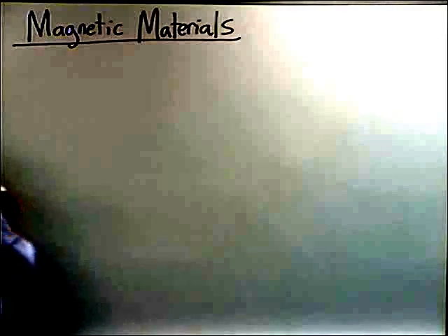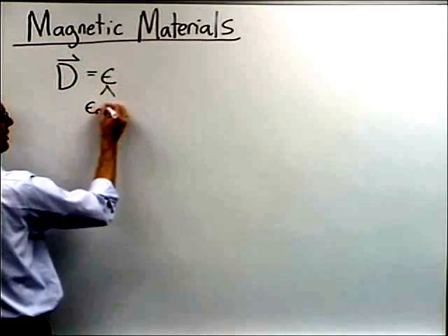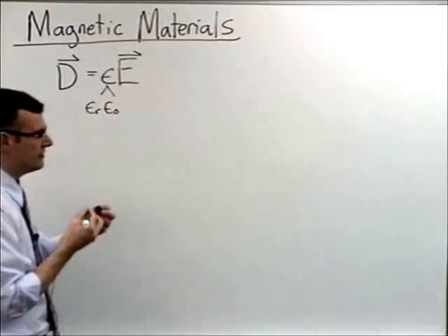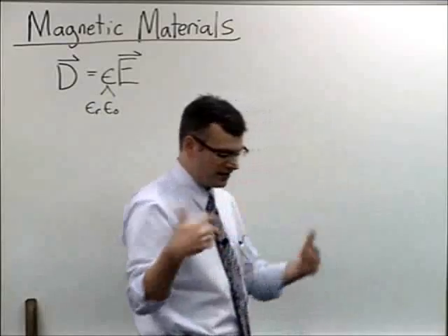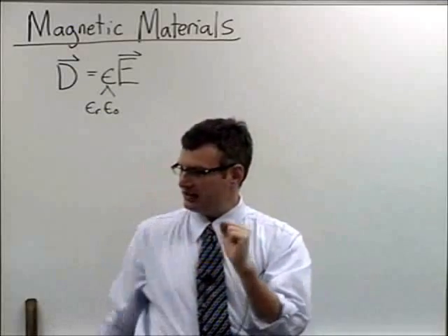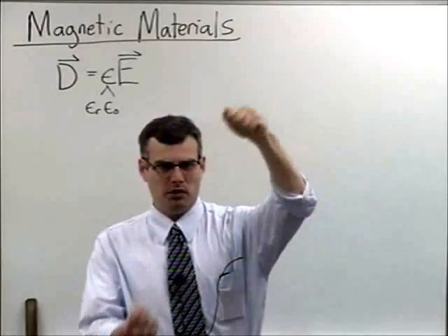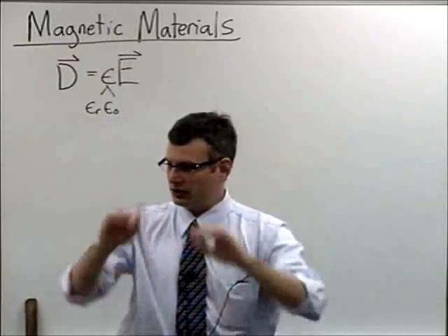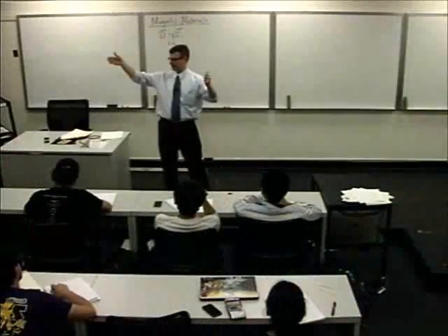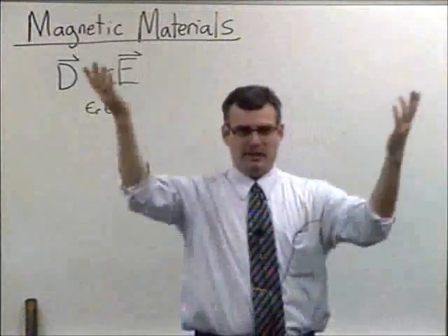We know from electrostatics, our discussion back then, that electric flux density is equal to epsilon, which we often write as epsilon r, epsilon naught, times the E field. And of course, epsilon r is always greater than 1. And we have a nice way of thinking about that, right? We understand that when you impress an electric field onto an atom, you're going to pull the positive nucleus in one direction and the negative electrons in another direction, kind of like a rubber band, and they'll snap back into place. The pulling of that dipole apart makes a countervailing electric field, which suppresses the total impressed field, and that means that the total electric field will be less than the original proportionality with the electric flux density. Hence, that constant of proportionality is bigger. You'll have a smaller E for the same amount of D field, and you get epsilon r greater than 1.